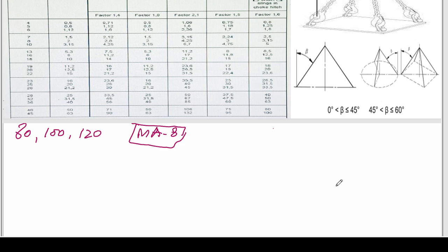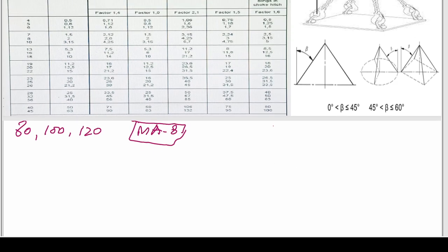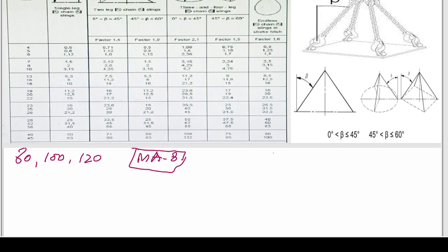Sometimes we use chains in chain blocks also. A chain block has a defined capacity, but ultimately it depends upon the chain you are using. The capacity can vary. Whenever we calculate the capacity, besides the alloy and the material condition, we should also understand how we are using it at the point of application. The lifting speed, lifting velocities and all such parameters are considered. One by one we will discuss how the load is calculated.